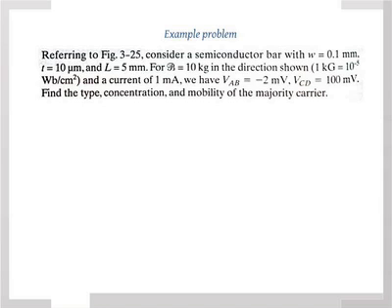And of course, to understand why that is the case, you have to look back at the last few slides and see what happens with electrons or holes. We did it for the holes. I suggest you do it yourself for the electrons, so you understand it. Okay? So the logic again, first, to see the type, look at the sign of the Hall voltage. Second, to calculate the concentration, all you need is the field, the Hall field, or the Hall voltage, basically. So it's given by current density, magnetic field, charge, and electric field. You know everything here.